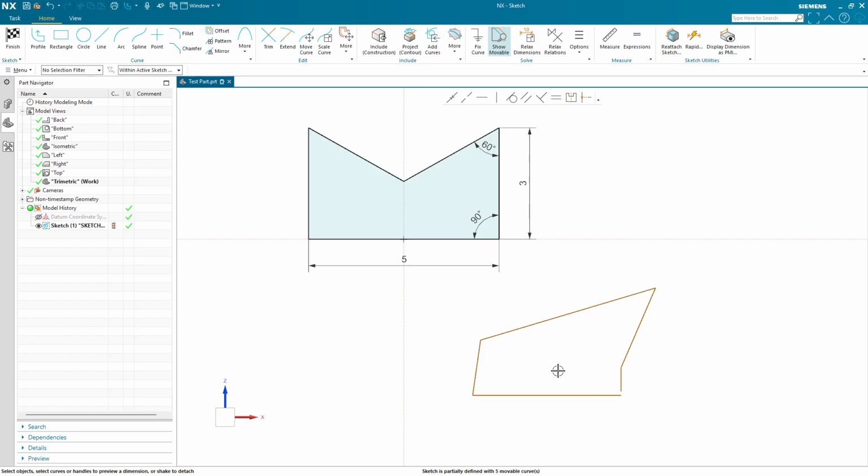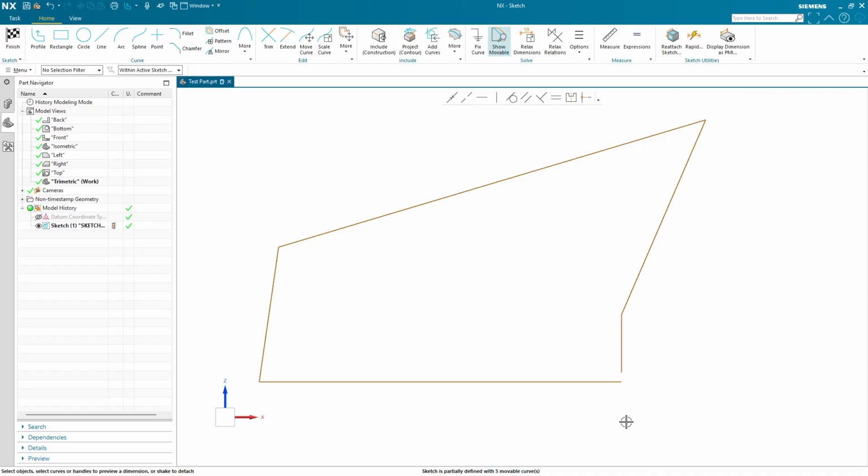There is no blue shading here. So when we try to extrude this into a solid object, NX is going to freak out. It's going to say, hey buddy, I can only make this out of sheet metal. You cannot have this be a solid chunk of aluminum or steel. There's no way this can be a solid object, sorry, because it's not closed.